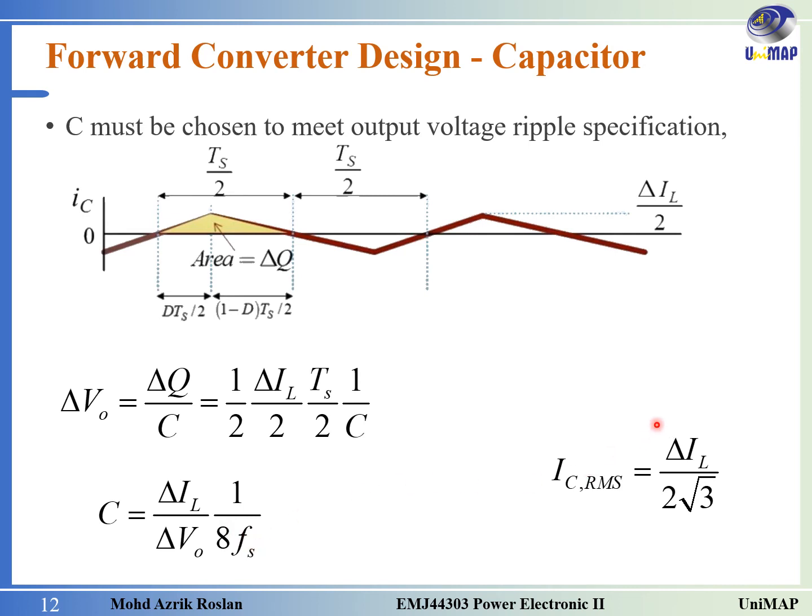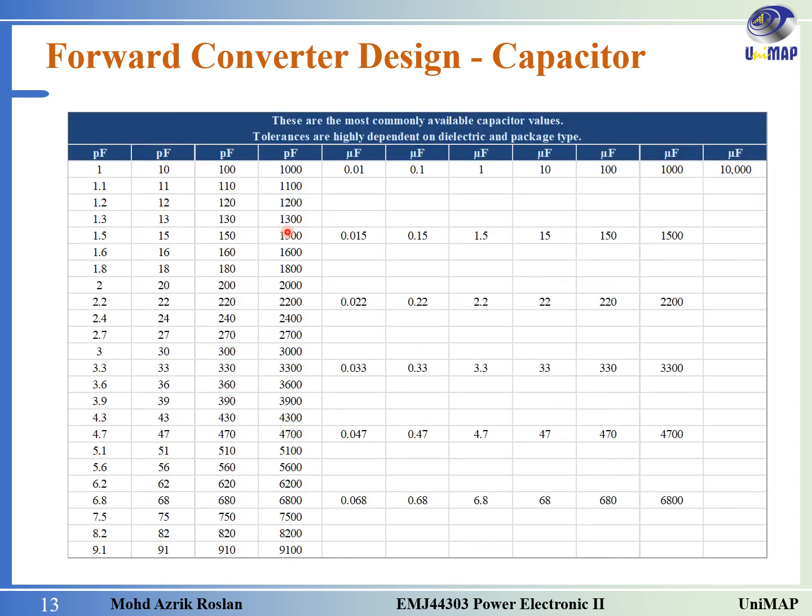Okay, and if we are required to find the IRMS, this is the equation for IC RMS. The same as with the inductor design, for the capacitor design we also have to use the standard value, and this one will be given. If we get a value that is not a standard one, we have to use one size bigger than the one that we designed.